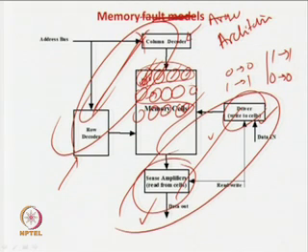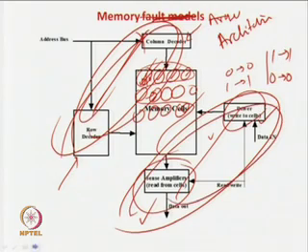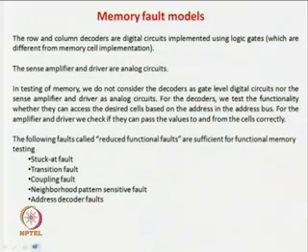If you sequentially write all parts of the memory cell, or in some predefined fashion, you know that I am writing this location, I am going to get back this location. So, in some predefined order which you know, you write out the memory and you read them back, then indirectly everything is tested. So, that is what we are actually going to do.